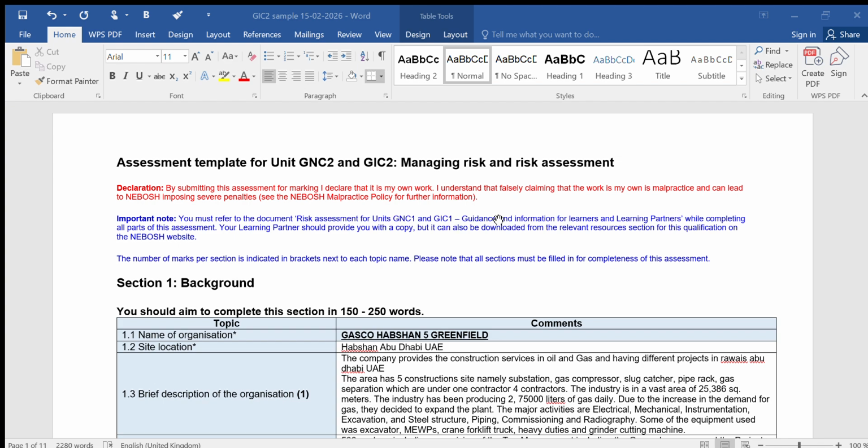When we install the acoustic enclosure and noise barrier, it will reduce the noise. Preventive maintenance: eliminate abnormal mechanical noise. Mandatory hearing protection zone: reduce exposure at individual level. Strict supervision and enforcement: ensure PPE compliance. Audiometric test: early detection of hearing damage. Apply the hierarchy of control: reduce reliance only on PPE and ensure long-term risk reduction.